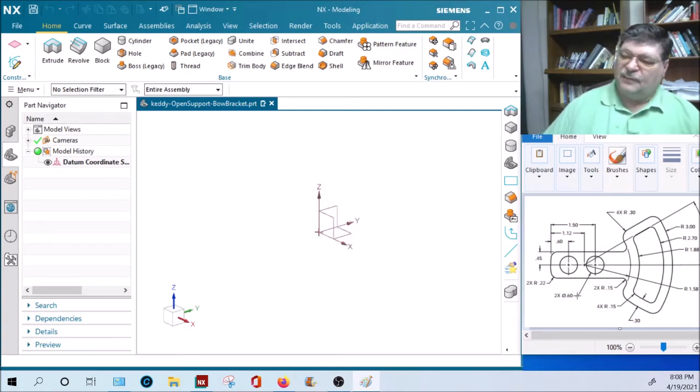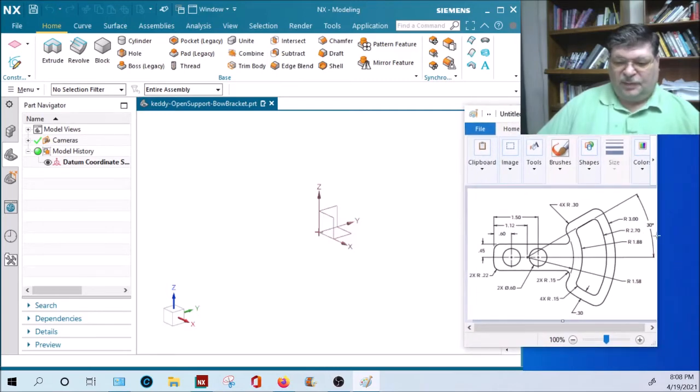You should read every dimension before you start a sketch. Make sure you understand what it's pointing to and what it means. Sometimes there's other symbols in sketches, diameter symbols, or R stands for radius. A circle with a line through it stands for diameter, if you didn't know. If I move this thing over, there's also a 30-degree angle from that line, or this line since it's parallel to it, to the center.